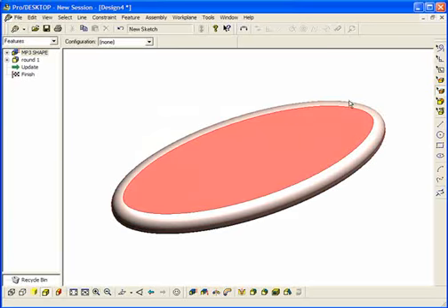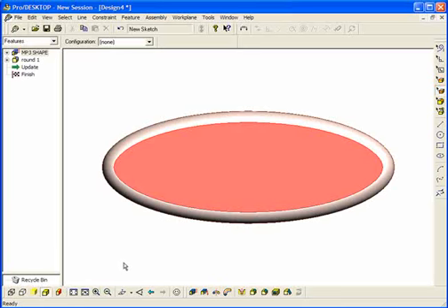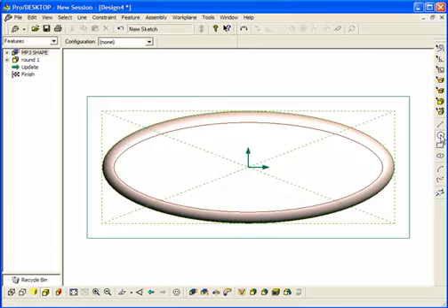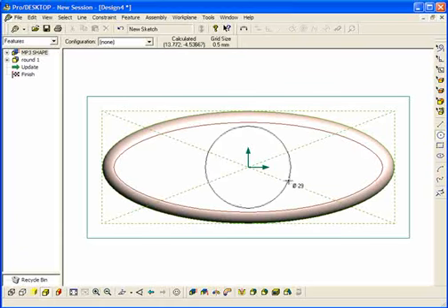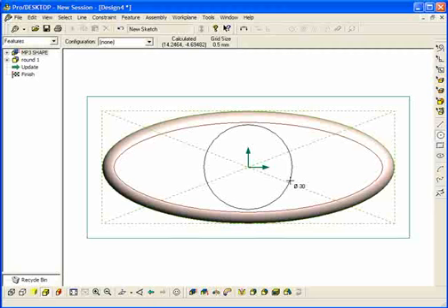We can now draw directly onto this new surface. Click on the View on the Work Plane tool, select the Circle tool and draw in the center of the ellipse. I have drawn a diagonal in the first place to create this ellipse, so this helps us to find the center. So I've drawn a circle of a diameter of 30 as shown.